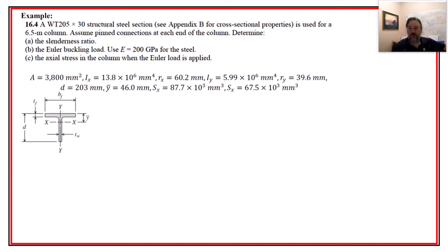We could show that with our I-beam, and I will pass this around in class, where you can see that it's harder to bend it in this direction than it is to bend it this way. That one is a stronger axis. This is a stronger axis about the x than it is about the y. So if that's the y, it's much more flexible. Its moment of inertia is smaller, so it will buckle that way first.